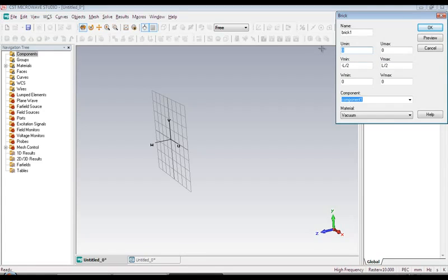And the width is considered along the U axis. The same technique is applied here also. Half of the width is along U minimum and the other half is along U maximum. The dimension thickness is along the W axis. However, you can specify thickness along the positive or negative W axis, but I would select the negative W axis and press the preview button to see the structure preview. And if you specify the thickness along the positive W axis and press the preview button, then the brick is located above the working plane.